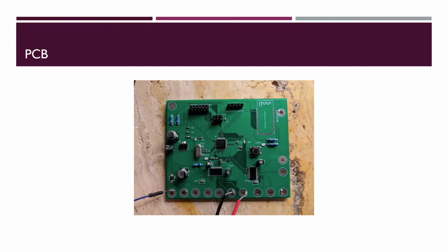This is our current PCB design. Our main microcontroller is the Atmega 328PB. The bottom two integrated circuits are Texas Instruments H-bridge drivers, the DRV8841s. They receive logical input from the microcontroller to control two sets of motors for moving the car. The empty section at the top right is our HM10 Bluetooth module. The Bluetooth module will communicate with the Atmega over a serial interface.